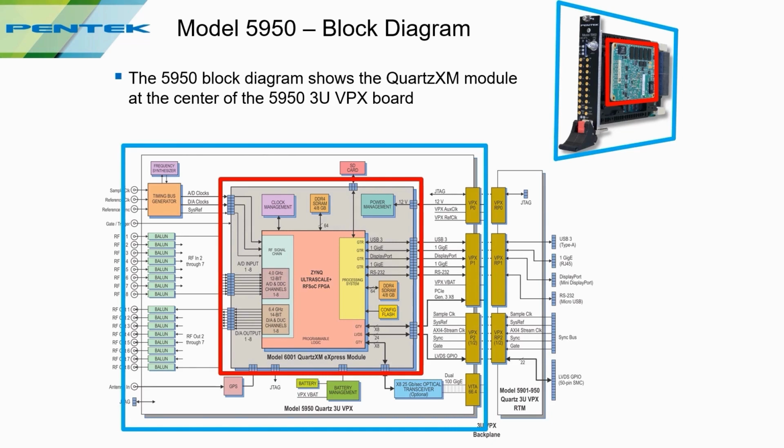There are transformers that bring the differential analog inputs and outputs from the RFSoC to front panel coax connectors, and you can see those in the photo on the front panel. There's an SD card which has the Linux operating system on it and also has space for user data. There are also 8 25 gigabit optical transceivers, and these are connected to the RFSoC's gigabit serial interfaces, and we support those with the installed dual 100 gig UDP interfaces that are part of the factory installed IP.